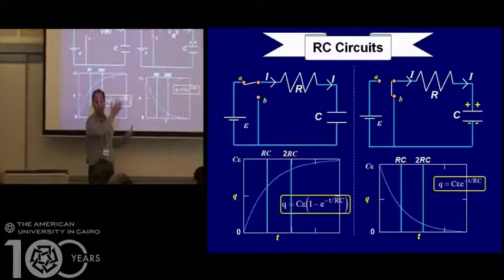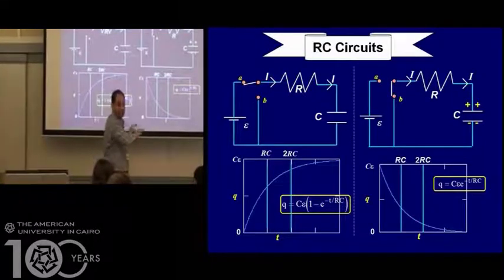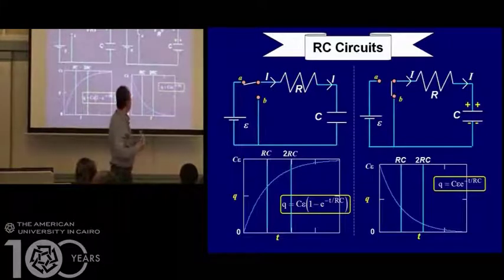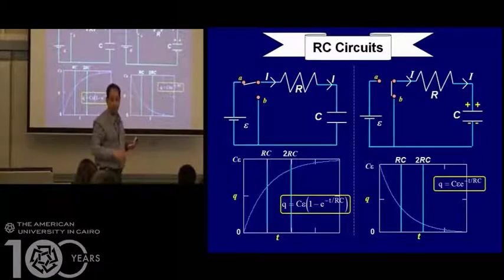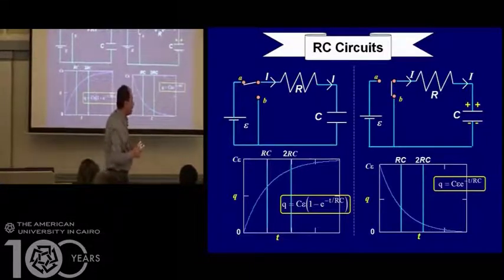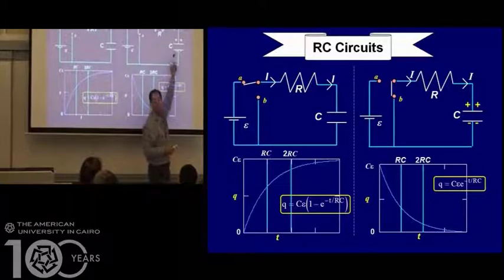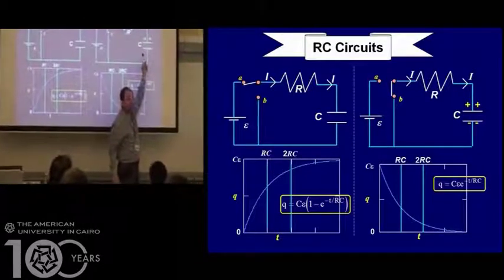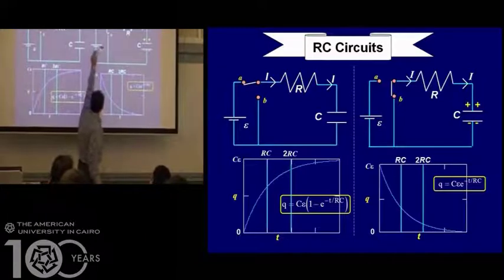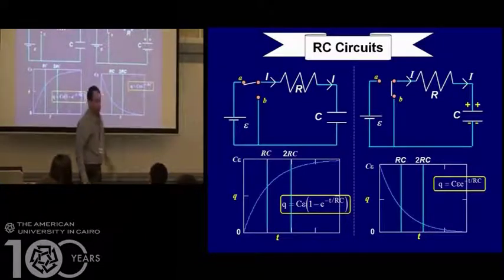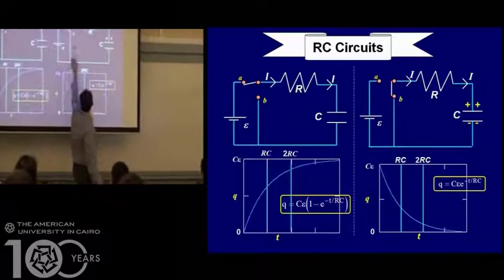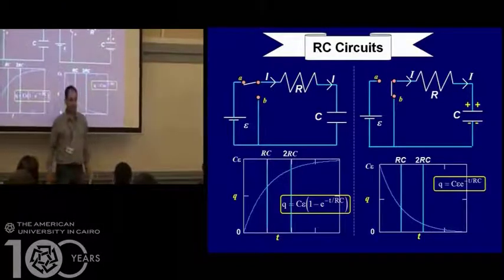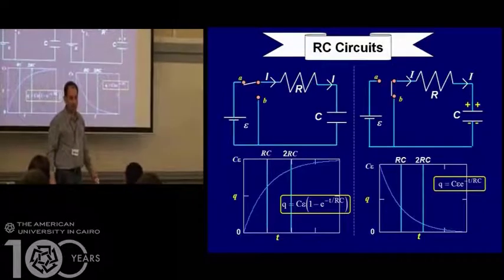Okay, that's when we are charging the capacitor. Now let's look at the physics again when we are discharging it. I'm going to assume that after a very long time of putting the switch to A, the capacitor is fully charged, then I would suddenly throw the switch from A to B. Now, at time 0, once you throw it to B, the capacitor will act like a battery.